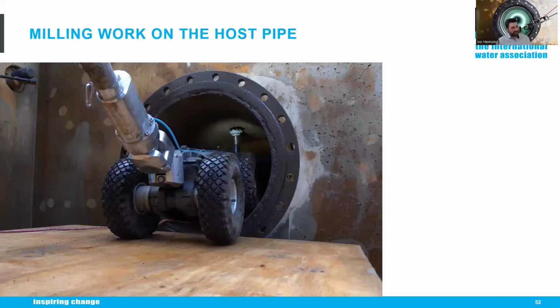Like Ari told us before, first of all, we have to clean the hose pipe. It must not be perfectly smooth and 100% round, but in total, we want to avoid sharp edges or obstacles inside. So we are getting robots inside, or pigs, or something else to clean, like water pressure, as you can see here in the picture.